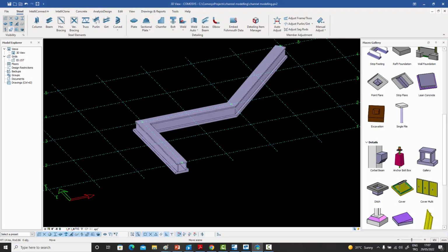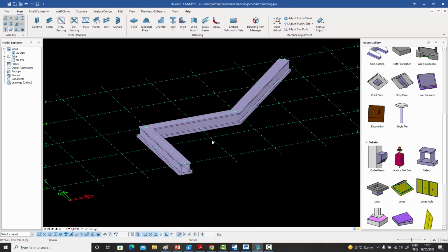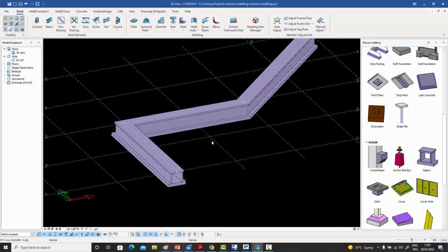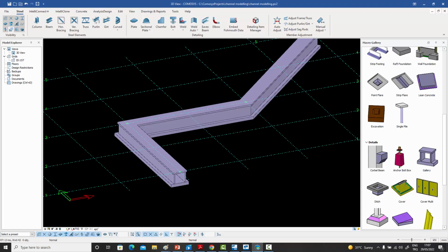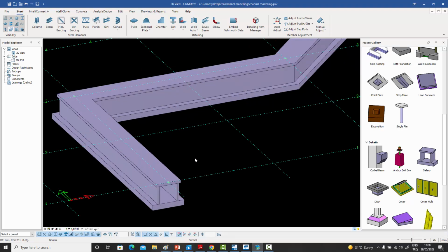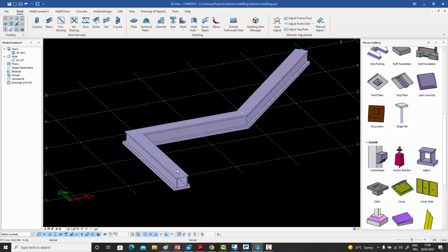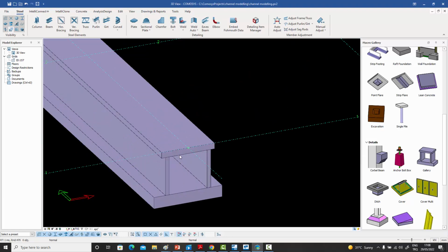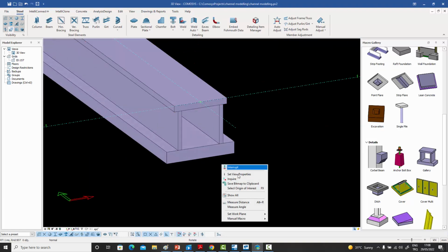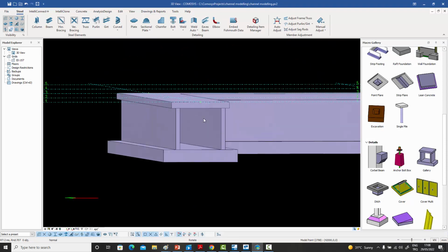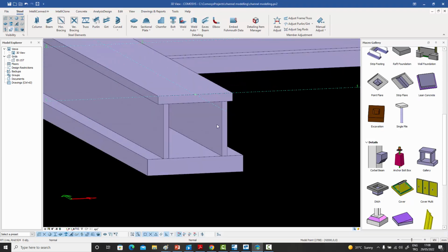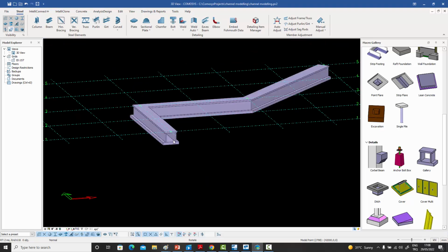Galleries are very common in industrial plants, and these could be underground galleries or overground galleries, depending on the situation. And they're typically used to carry pipes or electrical cables from one point to the other across the plant. This is what they typically would look like. So let me set the origin of interest somewhere over here, and so it's basically a gallery. And what you have is these cable raceways or pipe supports coming from the sides of the walls on which the pipes or the cables actually eventually run.